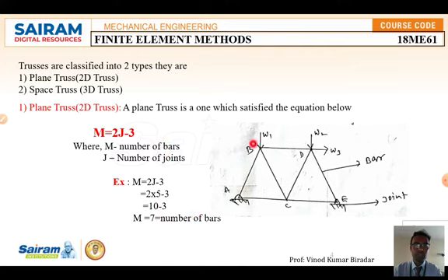This is the load acting here. One more thing is that in a truss element, the load should be applied at nodes only. Wherever nodes are there, only there are we going to apply the load. So this is about the 2D truss element.